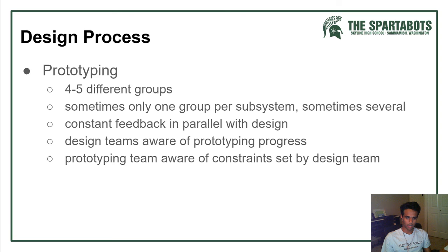Make sure prototyping is aware of the constraints set by the design team. So if it can only be a certain height, if the shooter can have a specific angle, if the intake can only be this amount wide, make sure the team that is prototyping is aware of these constraints while they're doing it, because if they're outside of the constraints, then the prototypes are basically useless to the design team.